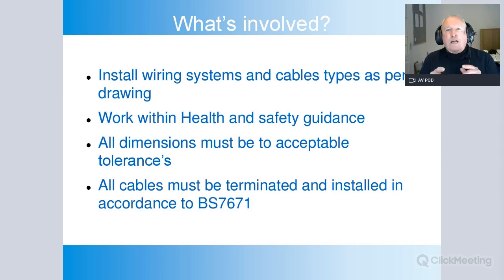And finally, all the cables must be terminated and installed in accordance with BS 7671. You're probably aware that's the regulation book. There are very specific regulations in there telling you how to install cables. If you don't follow them, you're potentially creating a fault, a fire risk and electric shocks.